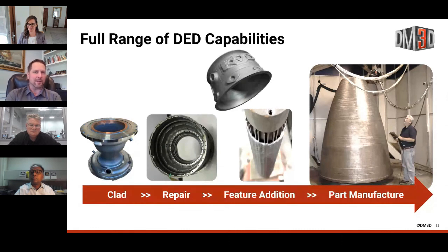And how does it transition? Because it's also not a uniform material card, if you will, or material property. As you start to alloy it differently, that material changes from layer to layer to layer, and then you have the material properties transitioning and affecting the overall thermal and structural response. So I would say the quick way to answer it is it's complicated. And this is just one piece, and we're really just hitting the tip of the iceberg. We're just starting to get a handle on how to approach these problems, and it's got a long way to go.